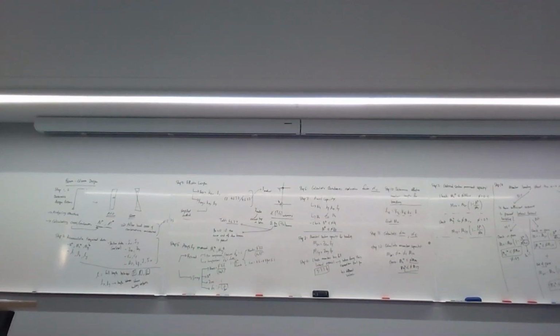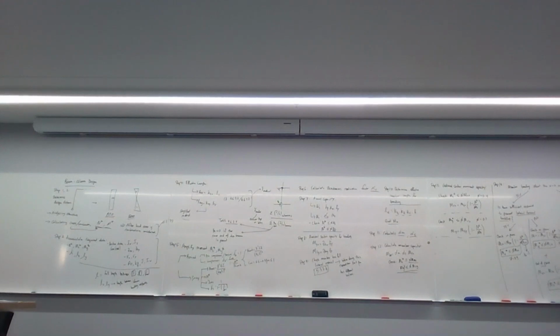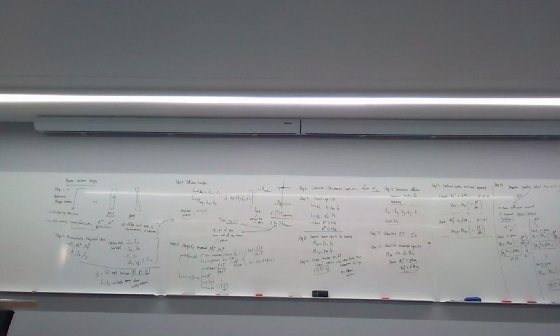Remember, biaxial bending means that you're applying stresses. That means your wind is coming from both sides. You have a column, and there's a wind blowing in the north-south direction and in the east-west direction. Only in that case is it biaxial bending. If there's only applied load in one direction, like an applied wind load in one direction, then this doesn't apply. But if it's no, then you're done with the question. If the answer is yes, there's one more pesky check that you've got to do.